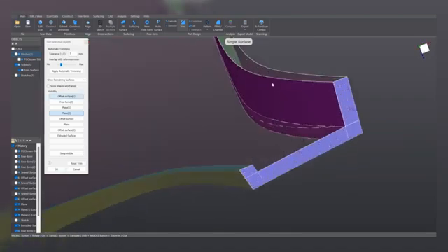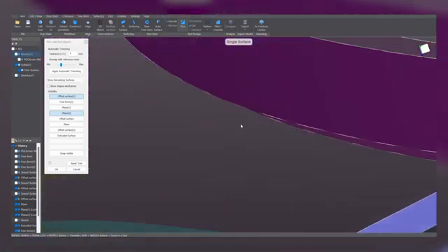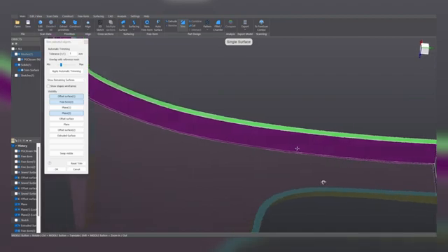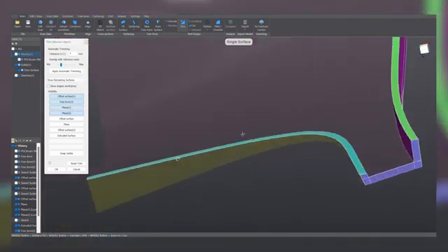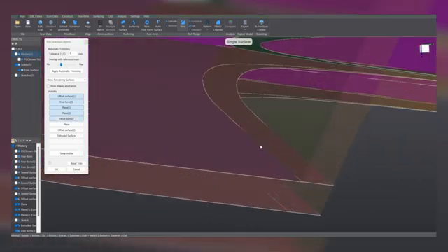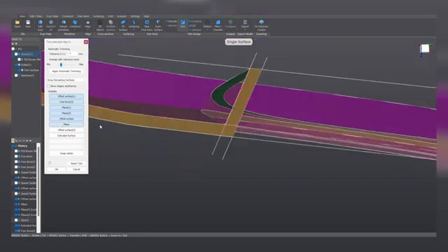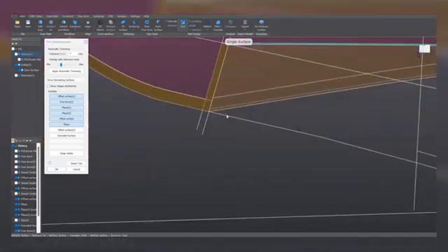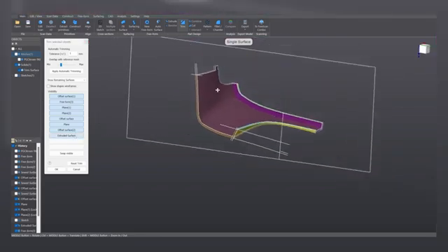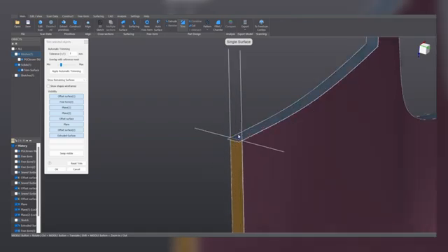Here we have exactly the same problem that we described. The surface on the left is going into the volume of the solid, so delete these faces. Okay, this looks clear. This plane looks good, no problems with it. The offset surface, watch out, it's going into the volume, so we need to delete this region. The plane here is well defined and well trimmed. Same for this offset. And well, we have this extruded surface, which unfortunately leads to this problem, right? But we are going to solve it now.